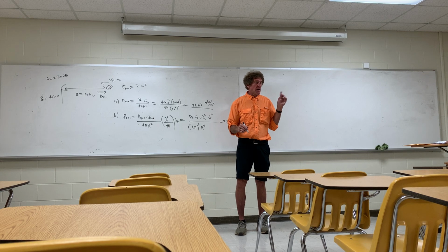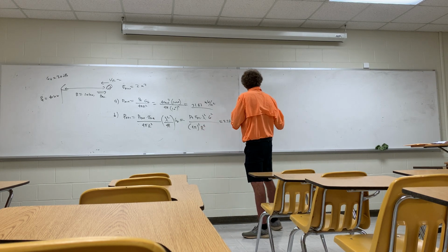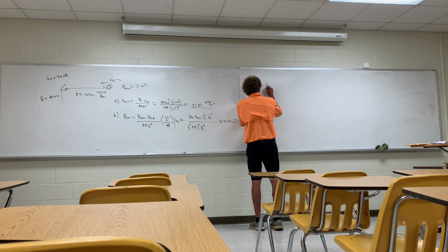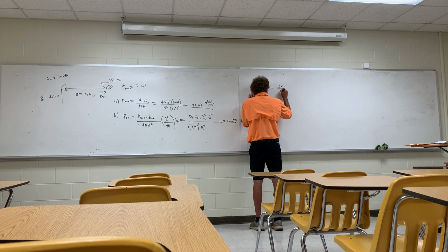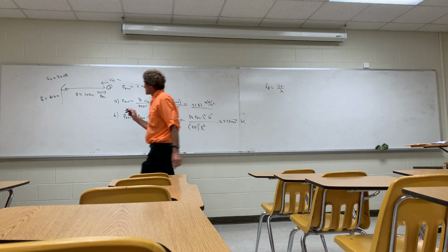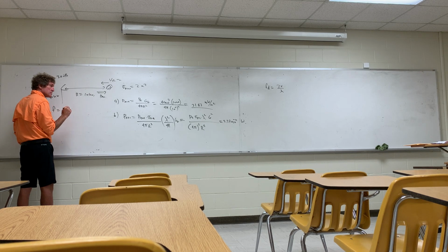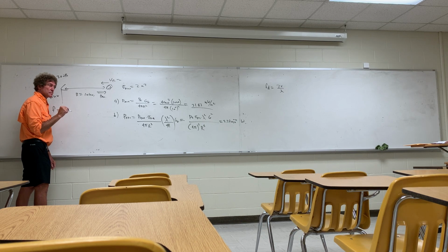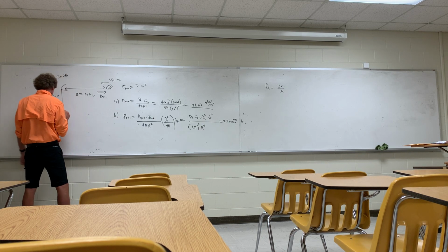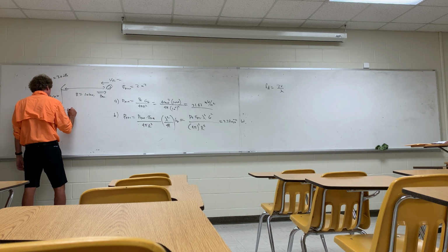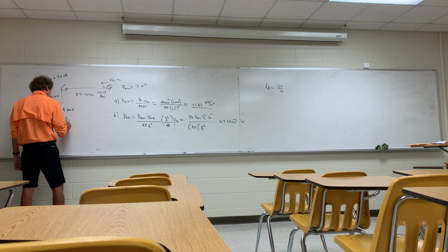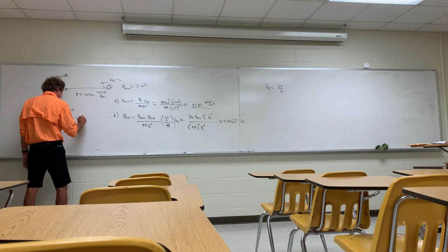Next thing I think was the Doppler frequency. Doppler frequency was based on 2v over lambda. So now we got to get lambda. What was the transmitter frequency? 4 gigahertz. 4 gigahertz, that means lambda is c over f, 3 times 10 to the 8th over 4 times 10 to the 9th.